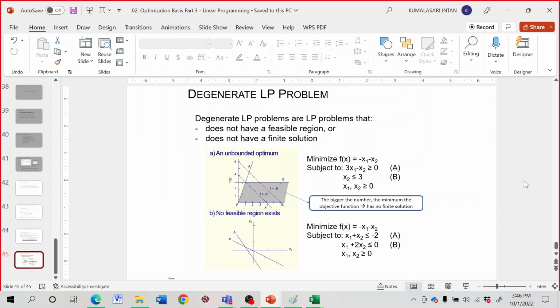And then we formulate that, and then we evaluate whether it is linear, non-linear, and so on and so forth. And then we can use Excel if we have decision variables of less than 200. If it's more than 200 variables that you want to find, Excel solver is not for you. You have to use a different software for that. And in Excel, you have GRG to solve nonlinear, Simplex for linear, and evolutionary algorithm for any other things that you cannot solve with these two.